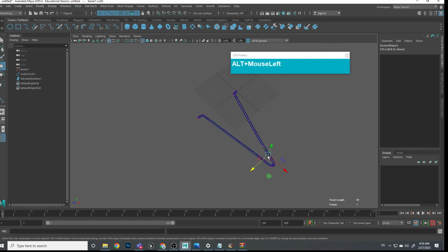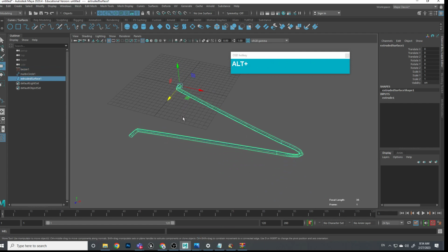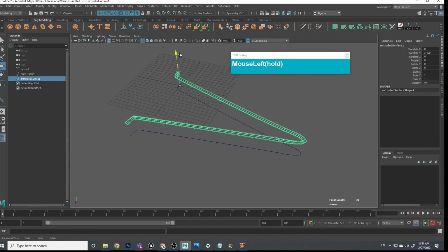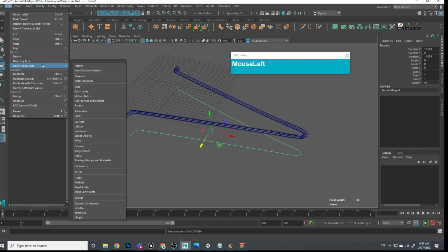do is we will first make this shape permanent. So to make it permanent, we have to delete history. So first, go and delete away the history, so that now this extrusion is permanent. It's not being affected by the curve anymore. So I can move the curve, it doesn't affect the shape anymore. So deleting the history, which you can do by clicking this button, or click on Edit, Delete by Type, History.